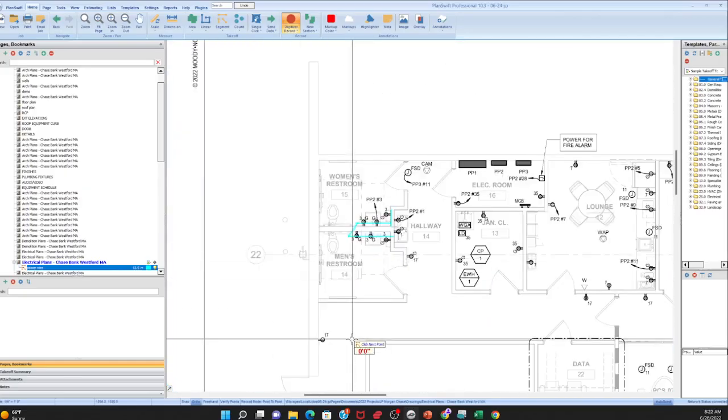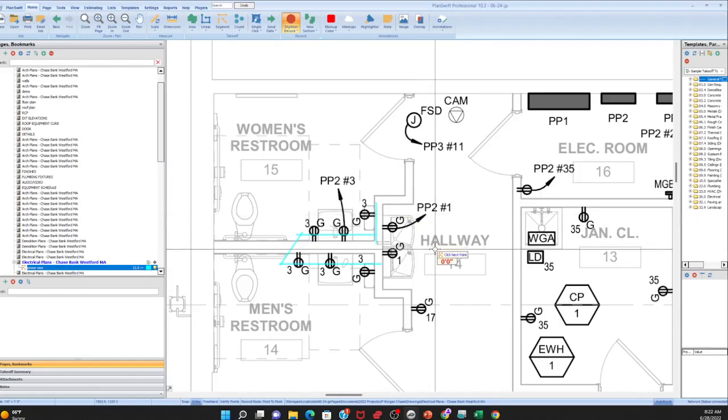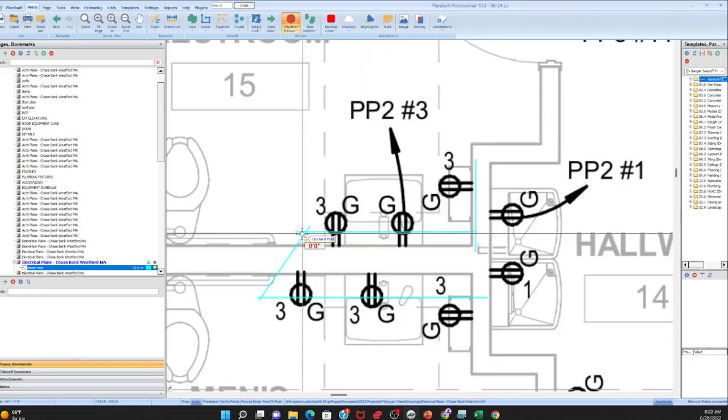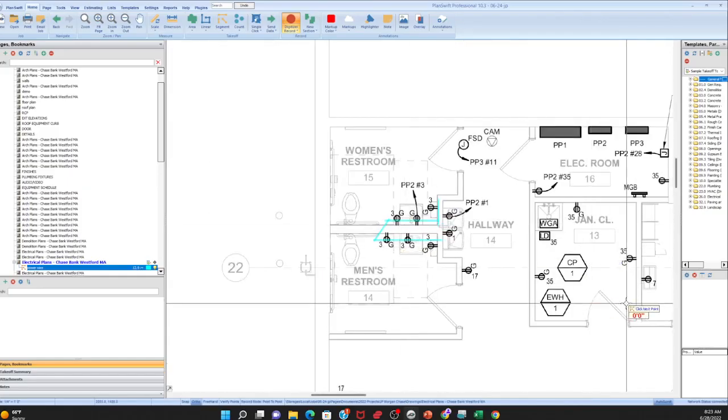So if I'm doing the power wire, there are 2 different types of power wire you do in the power plan. The MC cable, which you're allowed to use in these situations, but not in the home runs. Home runs are 9 times out of 10 a number 12 wire unless it tells you otherwise. Well, for lighting, it's usually 2 number 12s. But for power, it's 3: ground, hot, and neutral. So the wire configuration is always going to be 3 wire unless it tells you otherwise.